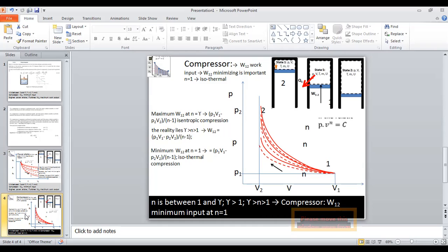So we will try to remove that energy by cooling the air. That is why compressed air systems can have fins or even heat exchangers to remove the warmness, the hotness of the air being compressed. Okay, making the air cooled down. Better than nothing. But water cooled is better than air cooled, because more heat can be taken out of the compressed air.